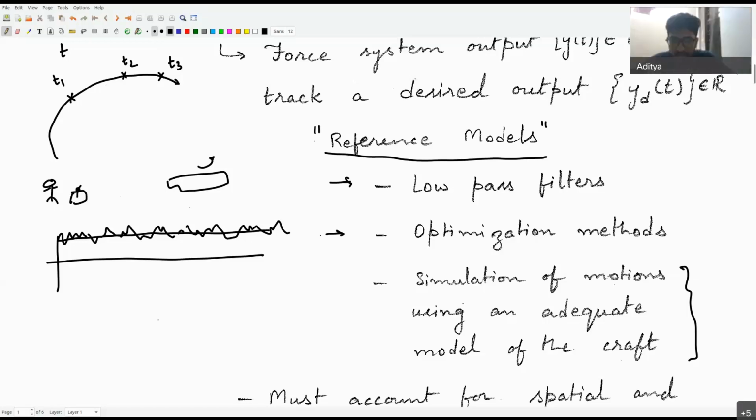So the remote control, when manually operating with the remote control, it will still do these fluctuations, right? So we are transmitting all those fluctuations also. Right now we are, which means that even if you actually observed our actual craft, sometimes when our deadband is not tuned very well, we may leave the joystick, but still the propeller will be slowly rotating with some speed.